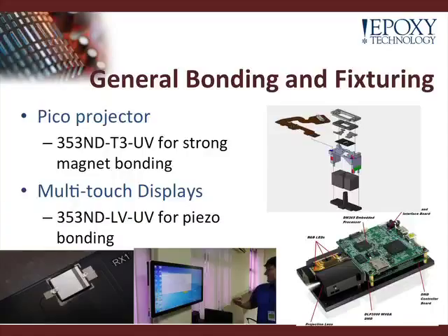But without the UV tacking, when you put these into the oven, they would pull together based on magnetic strength. Here they were able to utilize the UV hybrid systems to tack those magnets down, then thermally post-cure it without the need for an extensive jig system.